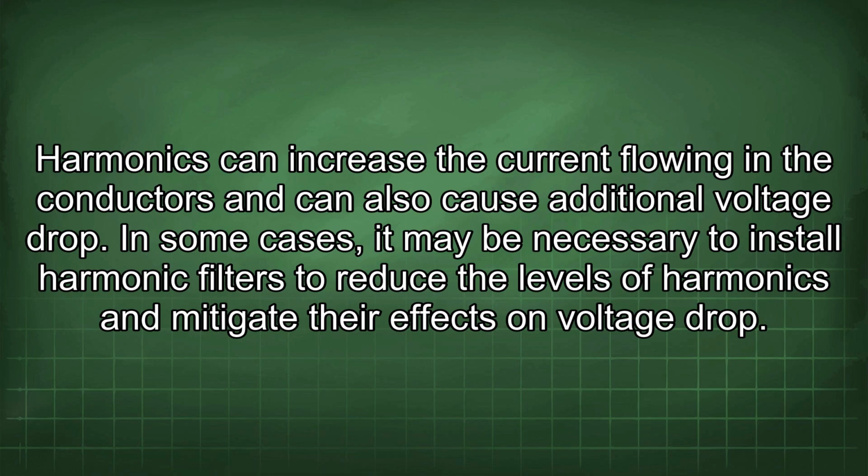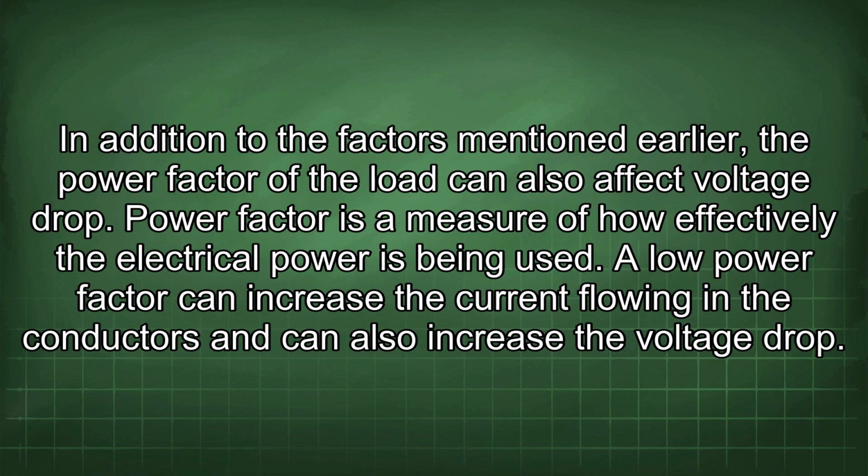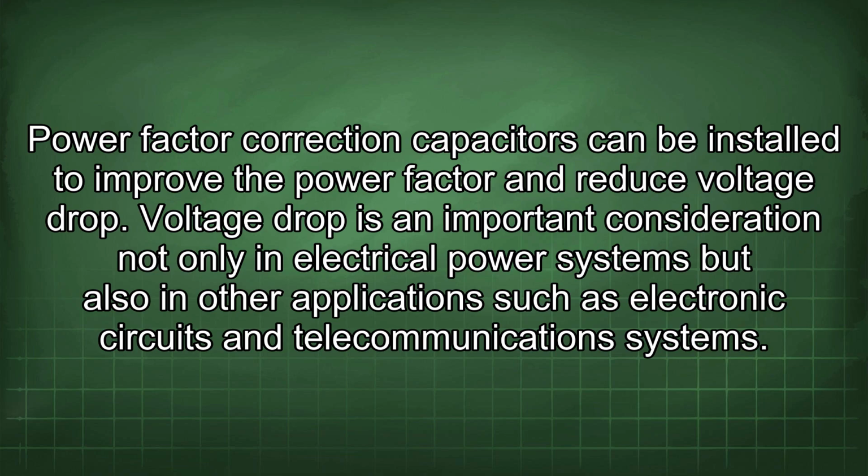effects on voltage drop. In addition to the factors mentioned earlier, the power factor of the load can also affect voltage drop. Power factor is a measure of how effectively the electrical power is being used. A low power factor can increase the current flowing in the conductors and can also increase the voltage drop. Power factor correction capacitors can be installed to improve the power factor and reduce voltage drop.